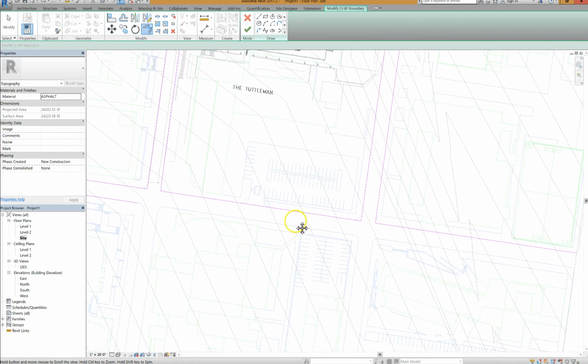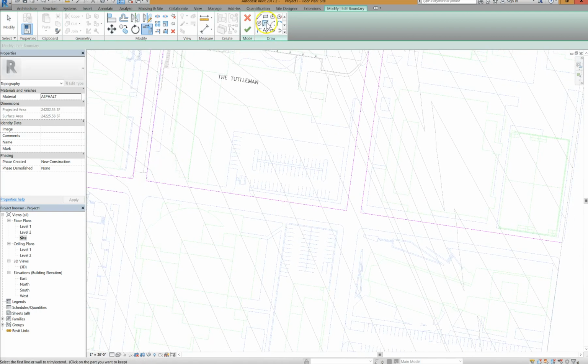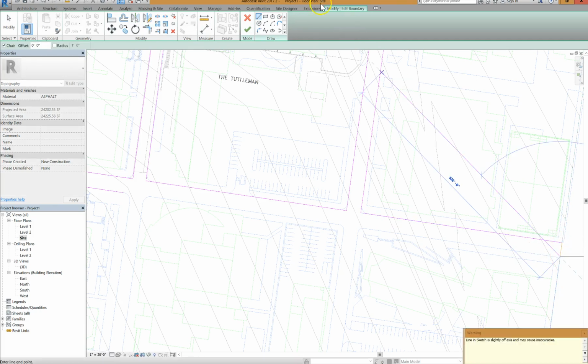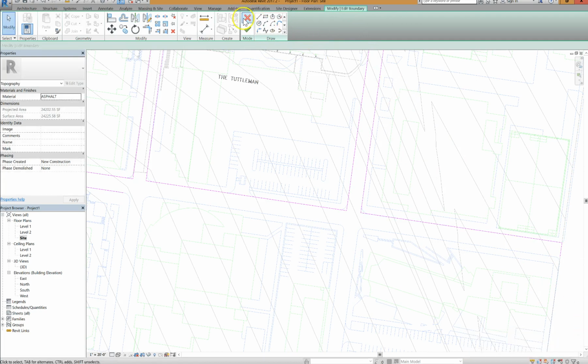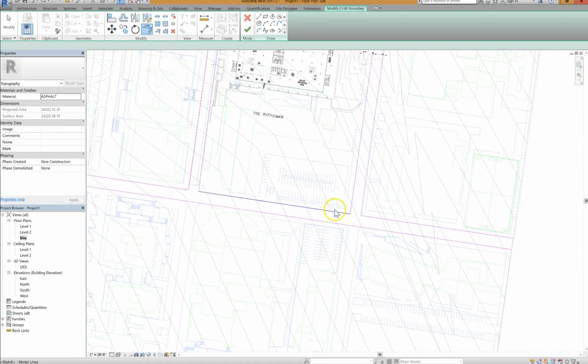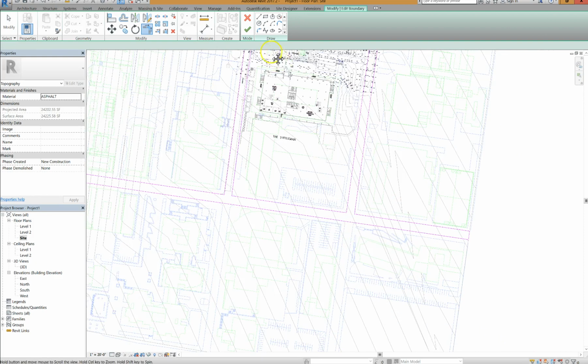And the nice thing is, this idea of drawing by just going into a sketch mode like this, where you have the check mark and red X. You're going to use that a lot. You'll see that we'll use that for making floors, roofs. We'll use it for a lot of different things, editing profiles.